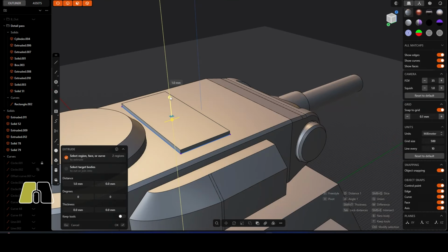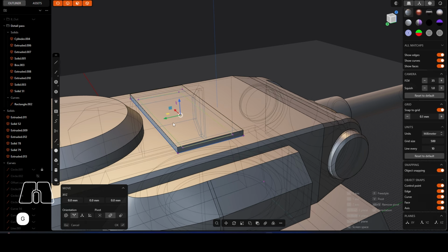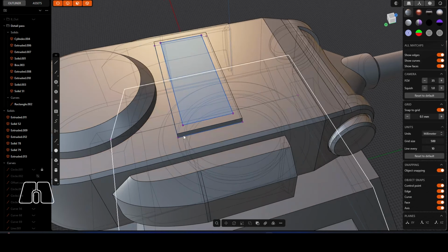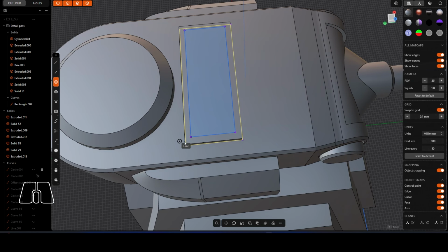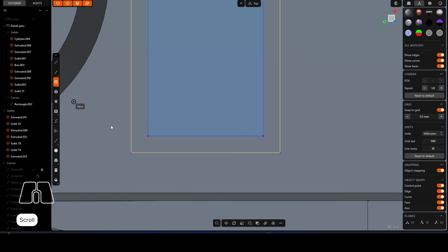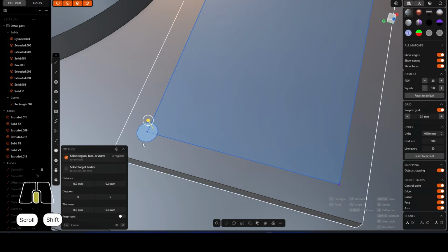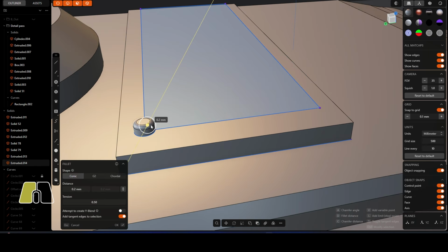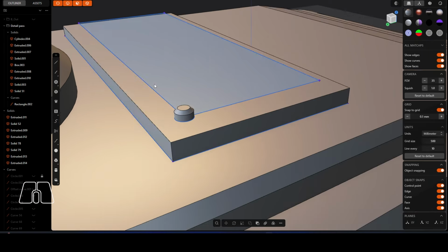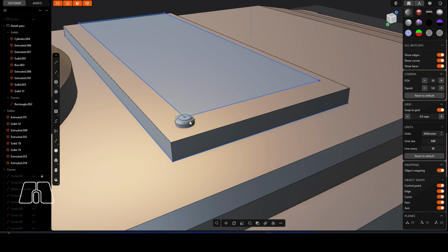So we're going to do that extrusion again like that, and then because we've got this piece underneath here, we can just move this up like that. Let's turn off the X-ray mode. So we've got that piece there. What we could do is grab this, do a bit of detail here, something like that. Do an extrusion like so. We'll just grab this, and again, little bolt type thing. You can do a bit more detail in your one. We'll just make sure that's merged down there. Let's get rid of that.